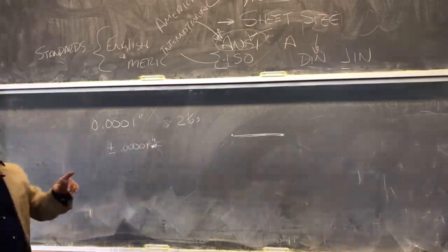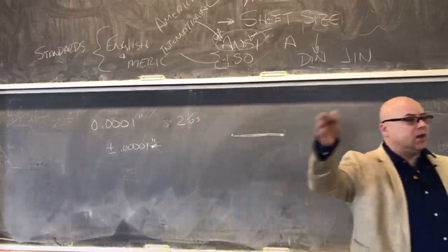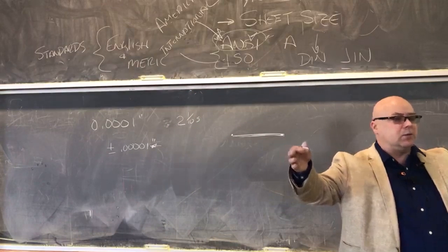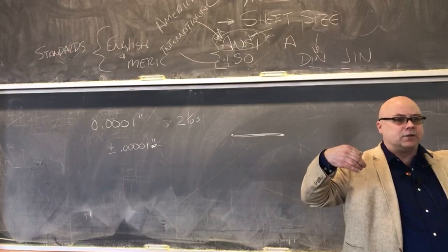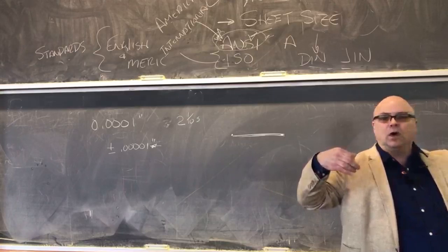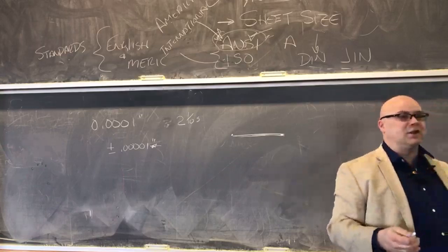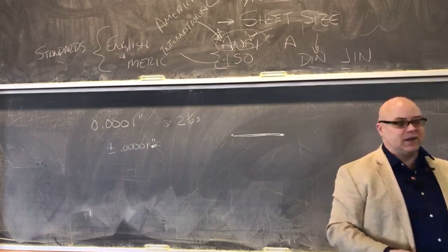Okay, so we need tolerances so that we can understand how much we can screw up the part that the designer wants. If we don't have tolerances, we as manufacturers cannot make the part. Or we can hand you the part because we can pick up anything that's on the ground and say, here's your part, if there's no tolerance specified.